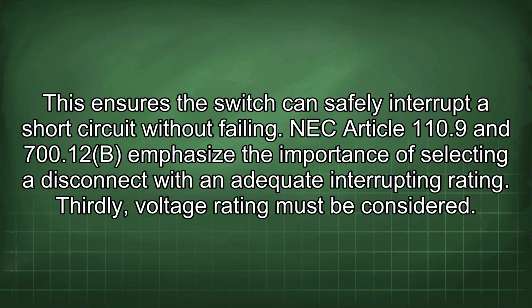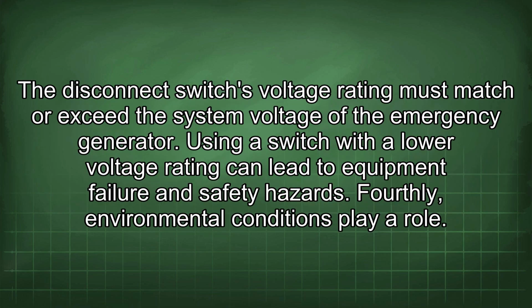Thirdly, voltage rating must be considered. The disconnect switch's voltage rating must match or exceed the system voltage of the emergency generator. Using a switch with a lower voltage rating can lead to equipment failure and safety hazards.